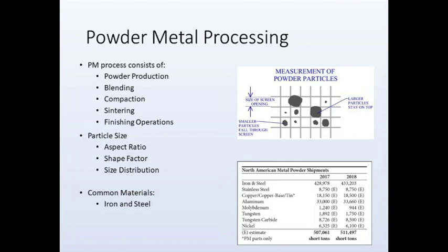So powder metal injection processing consists of a number of steps. First, the powder production. This is where you select the correct powder metal. You have to make sure it is the correct size that you want. This is a big factor in the density of your product, the flow characteristics of the fluid that is injected into the mold cavities, and the compressibility of it.